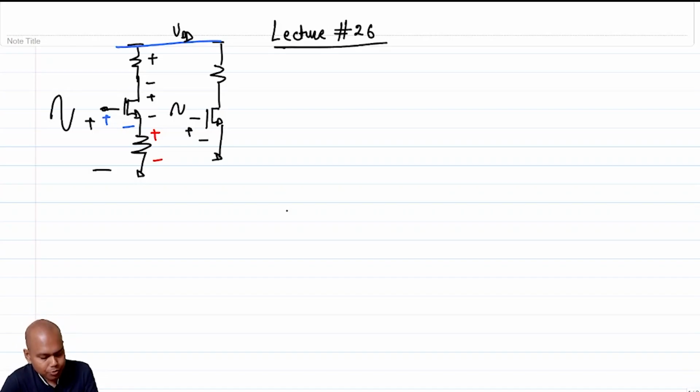So sometimes we make general arguments saying that a source degenerated MOSFET reduces distortion, which the statement in itself is not incorrect, but given the constraint of a finite power supply, you will often see that you will not be able to give a sufficient amount of quiescent VGS to that MOSFET, while with respect to a common source amplifier you can give a higher amount of VGS.